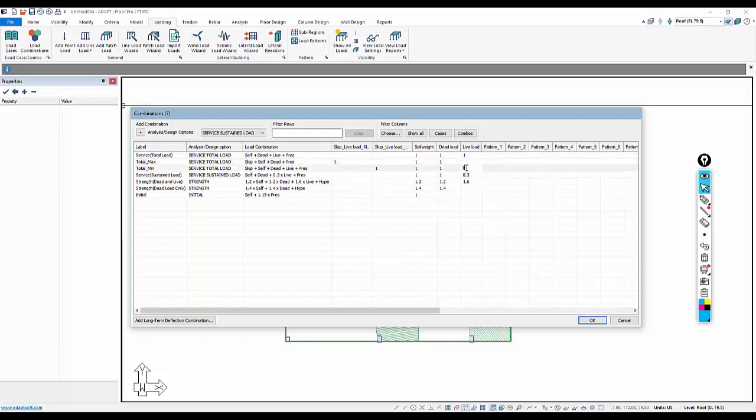This is the load case that we defined as being skipped. So we're going to just take our envelope of the live load that's being skipped, and I want to evaluate the deflection in the slab, just the linear elastic response based on these two cases. This here would just include live load everywhere. Now, for contour results, for deflections, for example, this is how we can set this up.